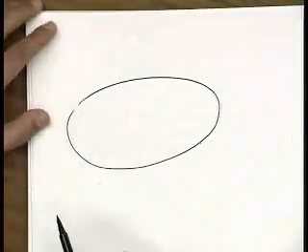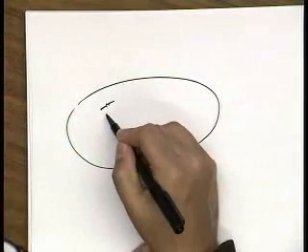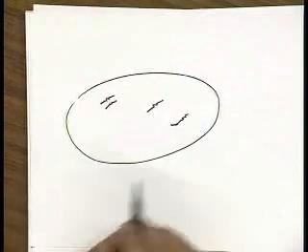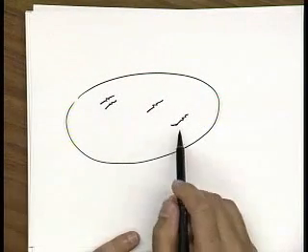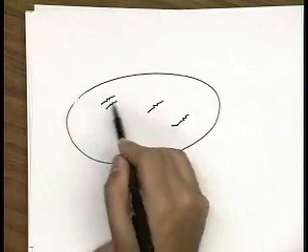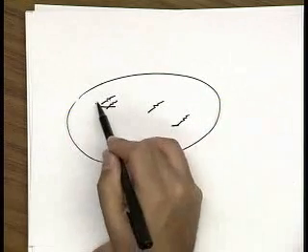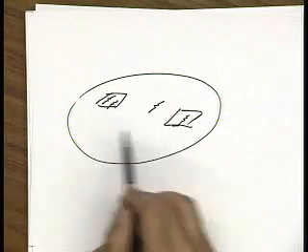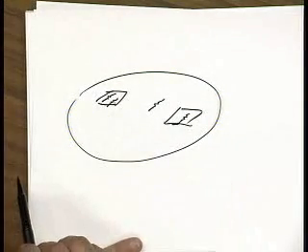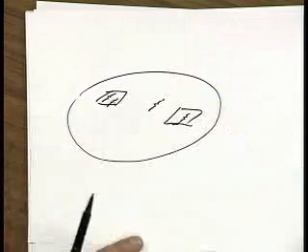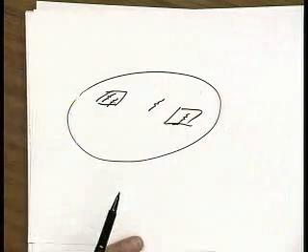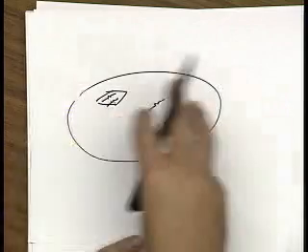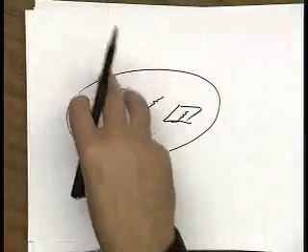So if this is my wafer, and I'm building resistors, there's one sigma which is the variation from one chip to another within a wafer. So if this is a chip and this is a chip, then they're on different parts of the wafer, and because of the way the doping is done, if you guys are interested, you can talk to your technology friends, in this class, it's never going to be uniform. There's going to be pockets where the doping is higher, where the doping is lower.